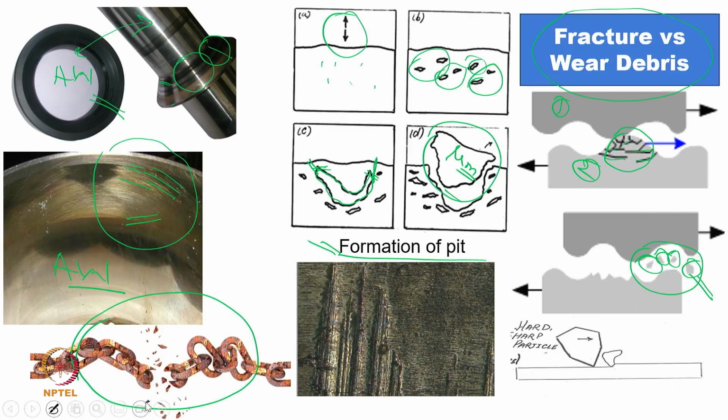Even if I am getting some sort of debris here, one particle, another particle, I can find out something is wrong, maybe corrosion is more dominating in this case, or maybe the thickness, or how many particles per unit time are coming out. If I look at the wear coefficient, I can really forecast the life or residual life of this chain itself. Before waiting for the failure of this chain, I can take a number of remedies, and that is the aim of this course.